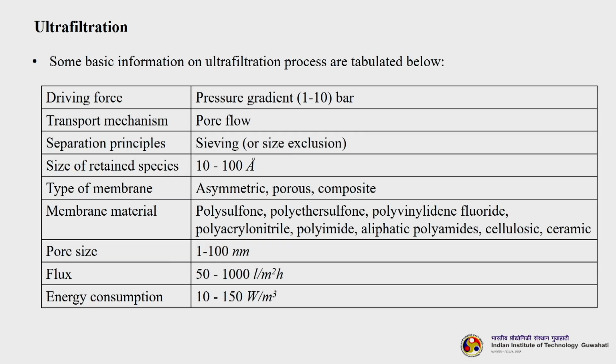So, these are some of the basic informations of ultrafiltration processes. The driving force is of course the pressure gradient, usually 1 to 10 bar. The transport mechanism is pore flow. Separation principle is actually sieving, or you can call it size exclusion. The size of the retained or rejected species lies between 10 to 100 angstrom. Membrane type can be asymmetric, porous or composite.